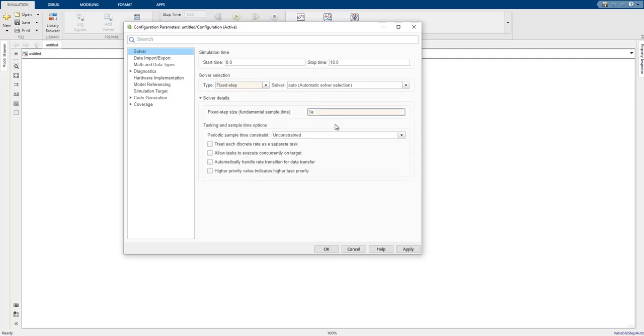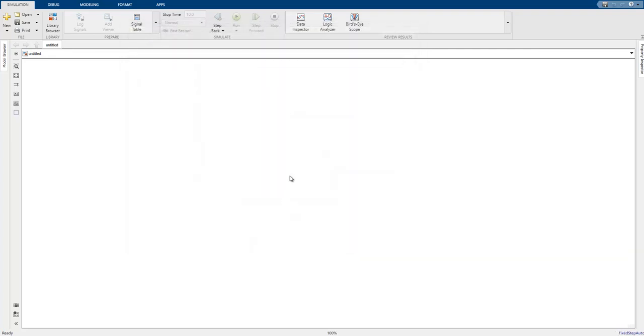1e-4 should be given at this time because it's the sampling rate of our system. If you choose the smallest values in here, then our solution may be wrong. Okay. Firstly, we need to create some Matlab function in here, like this one.